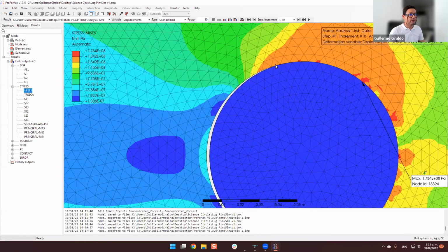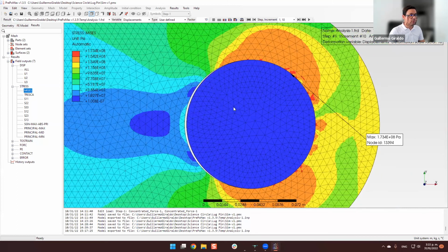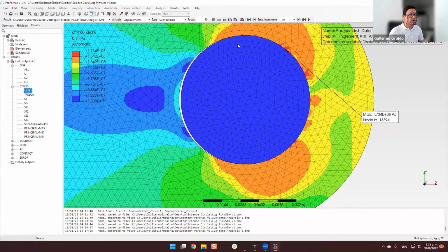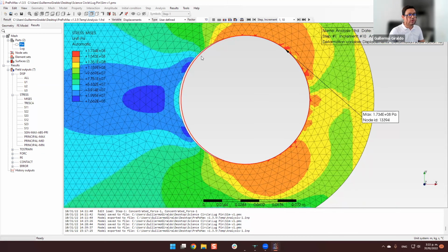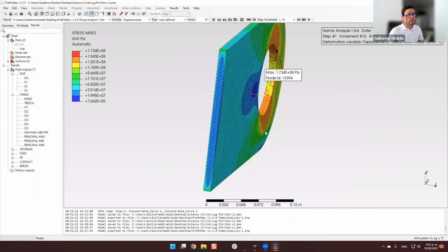A physical contact is a more realistic condition than what we call a bonded contact, where it pushes this region under contact but will also pull these together. And there is ovalization of the hole, as you can see here, which is very, very interesting.